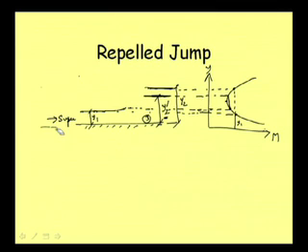This can be one situation, or there can be another situation, like we may have a sluice gate here, and water is up to this much depth here. We were having normal depth, but we are blocking it, and then we are allowing the y1 to flow here. We are doing it forcefully. So this water naturally will try to move to its normal depth, and that way it is always moving upward, and we have already discussed a lot how this flow can move upward.